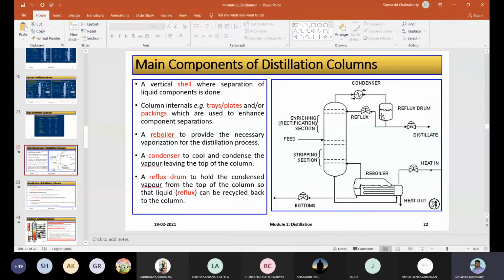Yeah. You see, this is the condenser portion. So under this puking condition, in excessive vapor flow, all the liquid is going to the condenser and then coming to this reflux drum. So the liquid level in the reflux drum is going to increase. No problem. So you are saying that if I close this valve and reduce the reflux rate, what will happen? There is going to be increased hold up in this reflux drum. That was your question, right? Yes, sir.